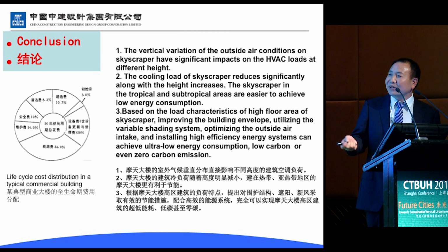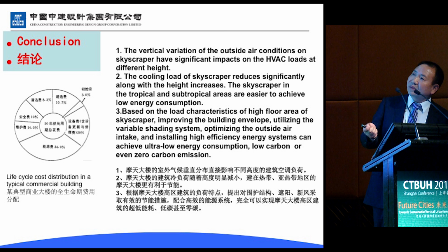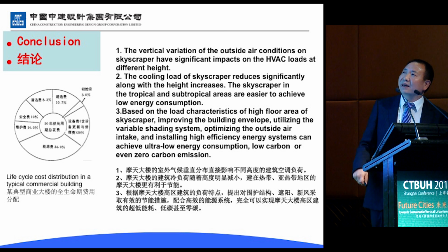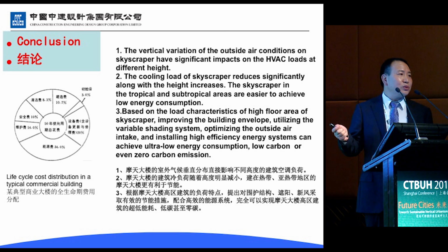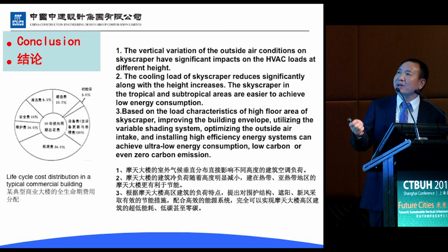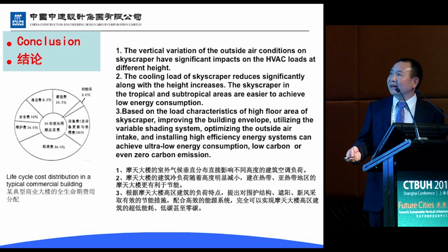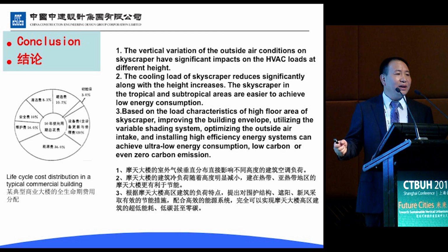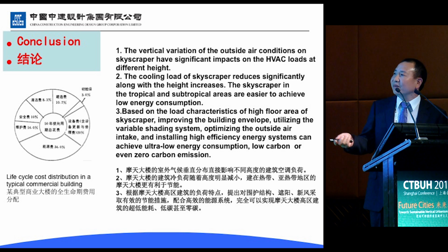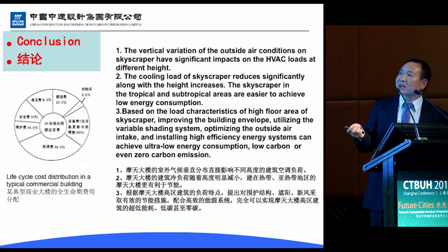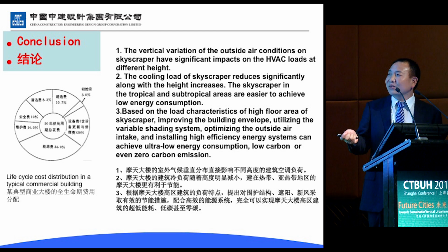So let me come to the conclusion. Now, the vertical variation of the outside air conditions on skyscraper has a significant impact on the HVAC loads at different height. The cooling load of skyscraper reduces significantly as the height increases, and skyscrapers in the tropical and subtropical areas are easier to achieve low energy consumption.